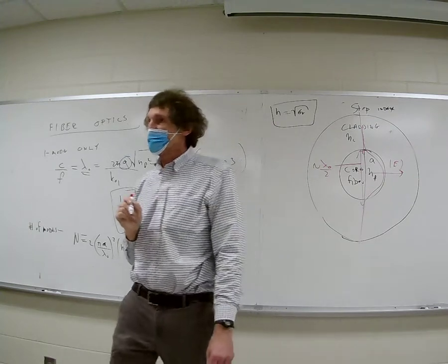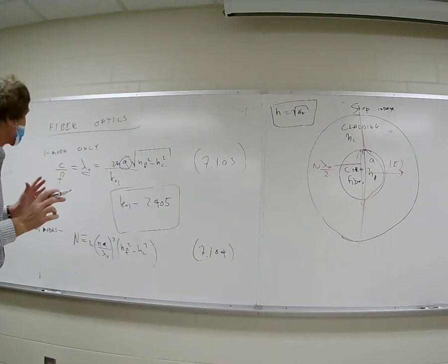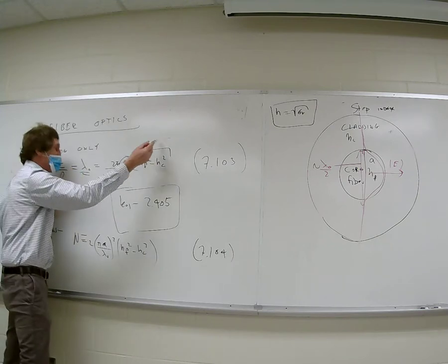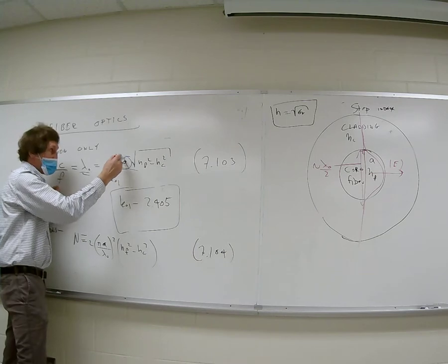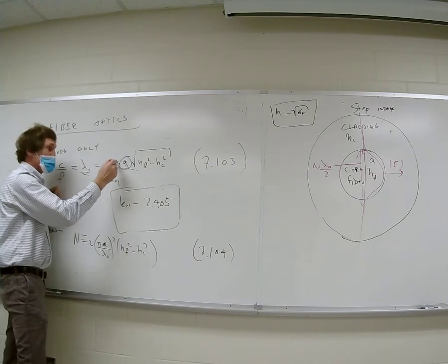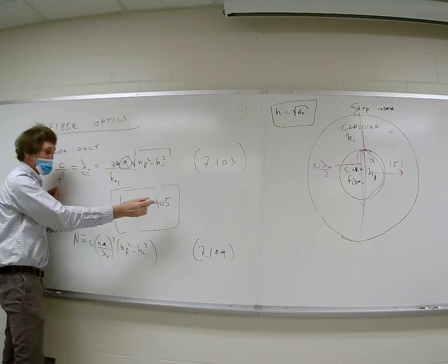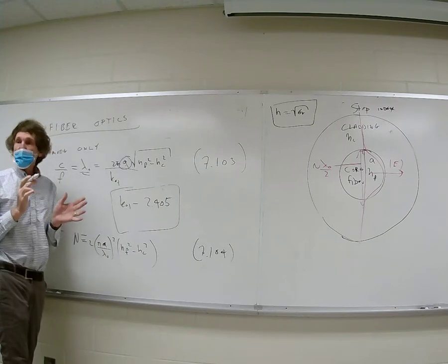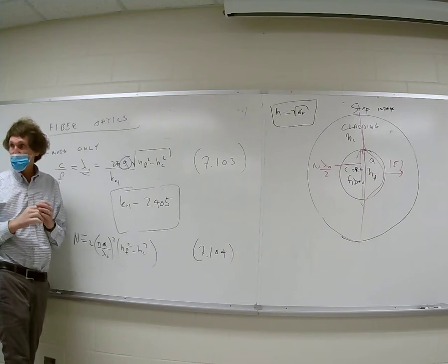It's very similar to that of free space. Rectangular guide, it's about, not quite. If you look at this equation right here, just think about this. If you set this whole thing, this radius here, equal to lambda naught over 2, you cancel the lambdas, the 2's cancel. I get pi over k naught. Pi is about 3.14, k naught is about 2.45. This will be a little bigger. What it'll do is adjust this parameter for that, but it's about that. So keep that in mind as far as the physics go.